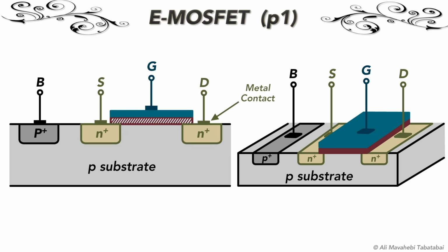You have to keep in mind that a MOSFET has 4 terminals. In many applications, we don't care about the substrate, so you can change drain and source terminals because, as mentioned before, the device is symmetrical. However, there are times that one of these terminals is connected to the substrate. In this case, the terminal that is connected to the substrate is the source, and the other one is the drain. Therefore, in this case, we cannot change the source and drain terminals, and the terminal that is connected to the substrate is always the source.